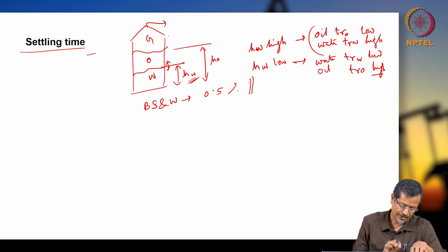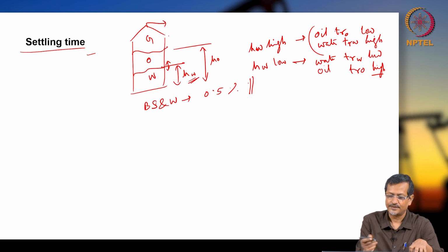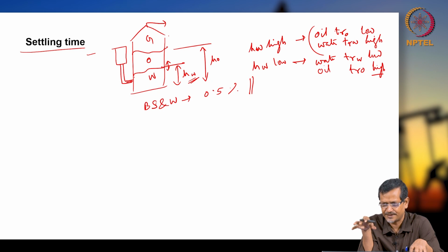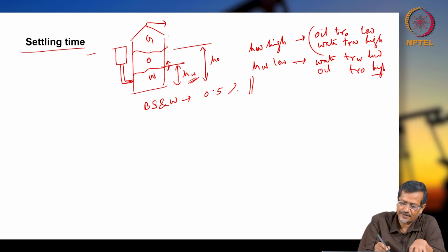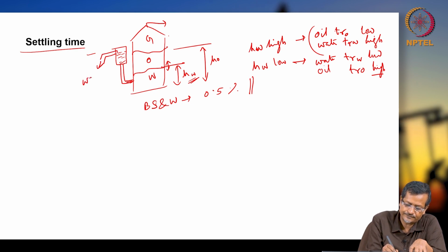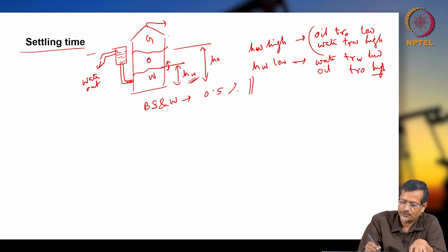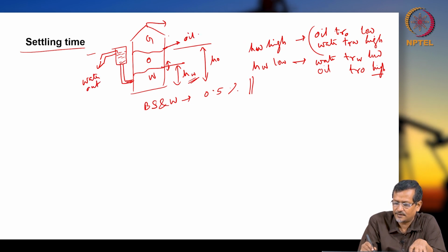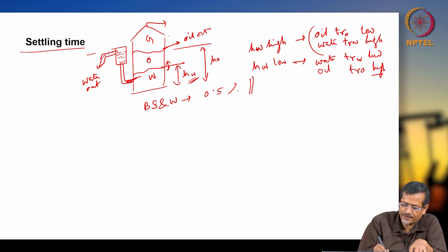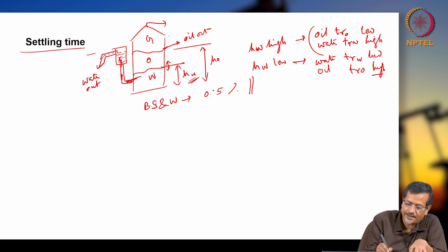Interface level, okay. Now, interface level is controlled using a water leg. So, there will be one water leg actually, normally a water leg will be there. Because controlling everything inside the separator is difficult, there will be one water leg. So, the water level will be rising up here, okay. Then from here you can create a weir and take the water out, okay. Oil you are taking from oil out, and water you are taking out from here actually. Water is going this way, and you are maintaining it on the weir, and the water will go out, okay.